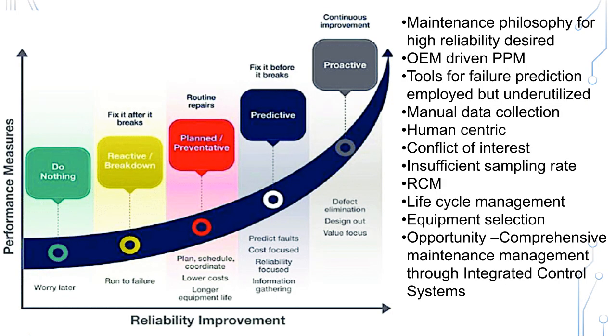So how is this function of maintenance being done till now? With the main objective to maintain high reliability of the ships and their equipment, the maintenance philosophy adopted plays a very critical role. Currently, planned preventive maintenance recommended by the OEMs is followed in the Indian Navy, as was also told in the Air Force. Tools like oil analysis, vibration monitoring, parameters trending have been adopted in the Indian Navy. However, there are gaps in effective utilization of these towards the final objective of highly reliable equipment.